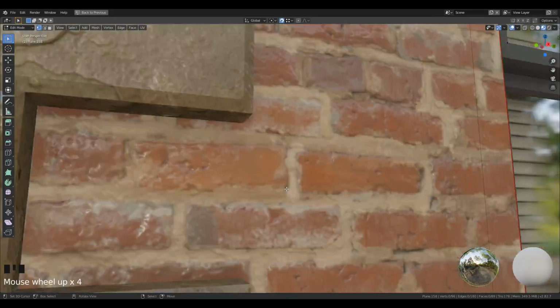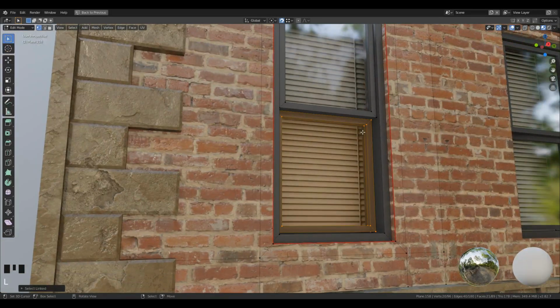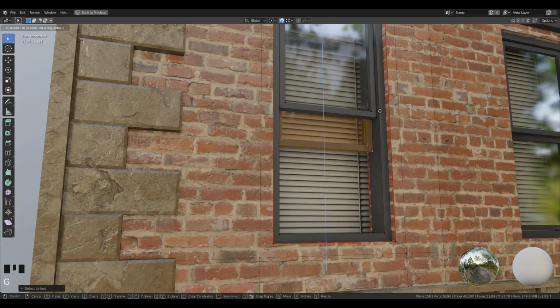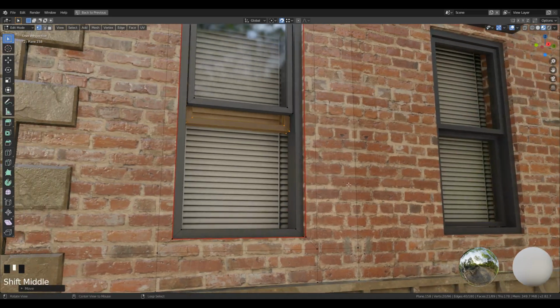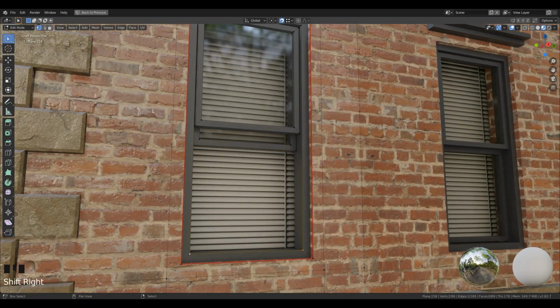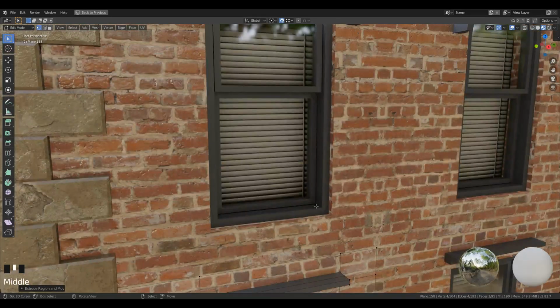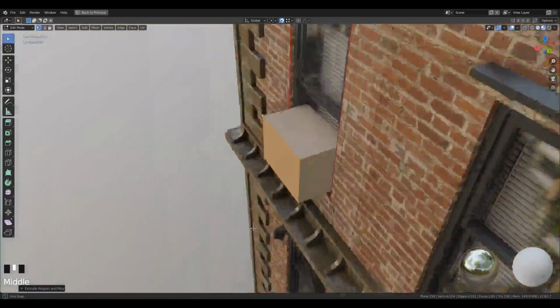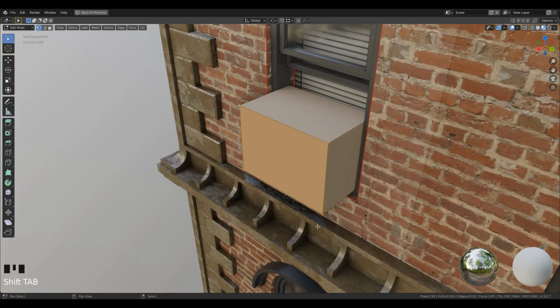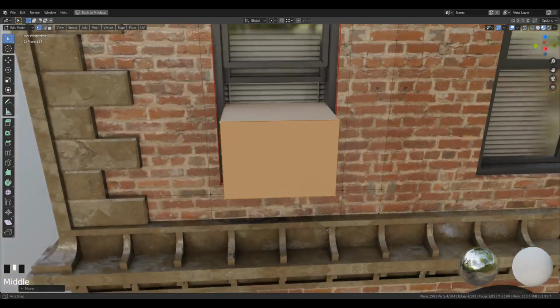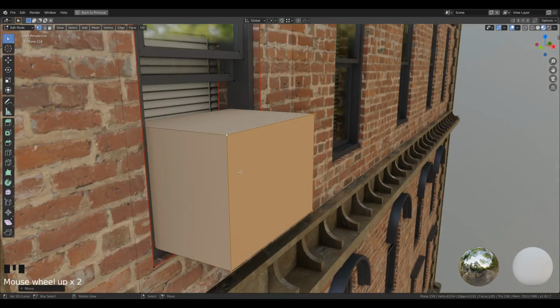For creating the window outer unit, just select one of the windows and slide it up to have more space for the outer unit. Then just duplicate the lower edge and extrude it up. Then just define the distance of it and then just extrude it out. After that, use inset, and you can use edge loops to create interesting shapes and then later extrude it in.